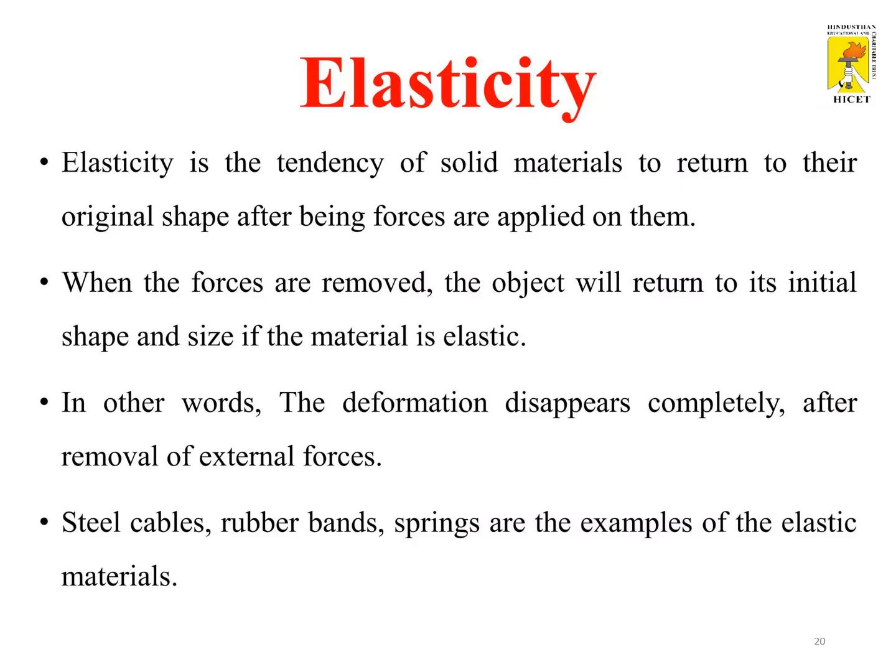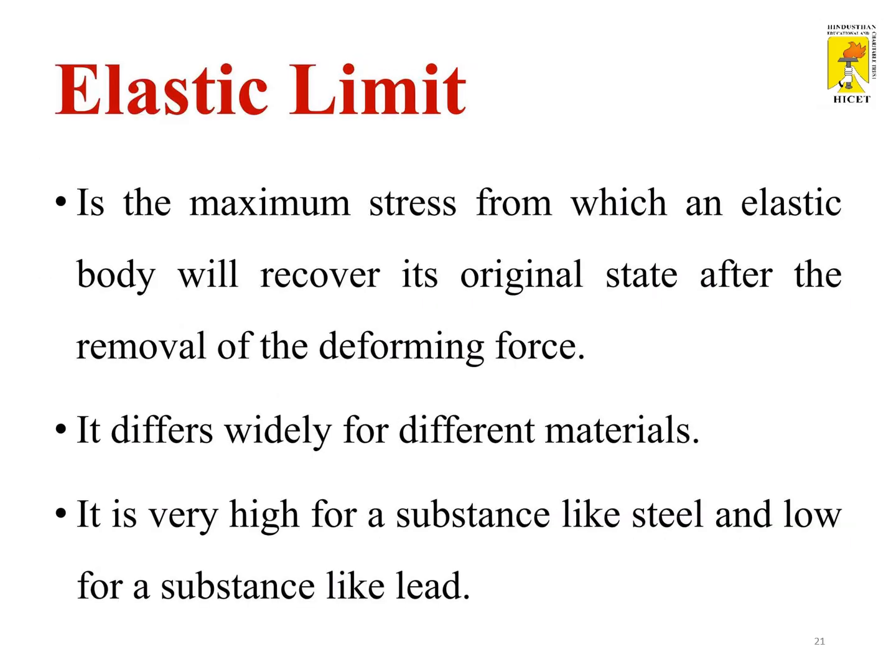Elasticity is the tendency of some solid materials to return to their original shape after the applied forces are removed. When the forces are removed, the object returns to its original position. In other words, the deformation disappears completely after removal of the external force. The elastic limit is the stress up to which the elastic body will recover its original state after removal of the deforming force. This limit is called the proportionality limit for the member.